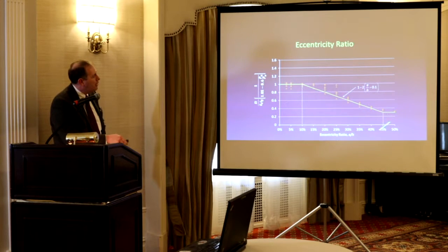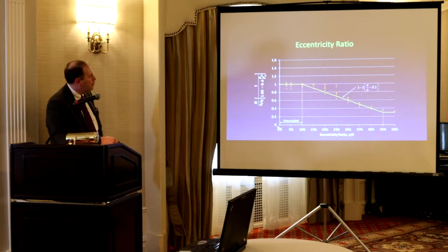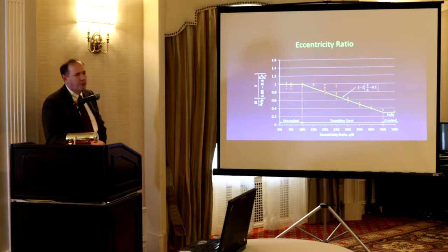So we found out we could represent this in this dual banded range. Uncracked, we don't worry about the eccentricity up to 10%. And then if you have some higher eccentricities, we could come down this transition zone, represent it, and then ultimately fully cracked.